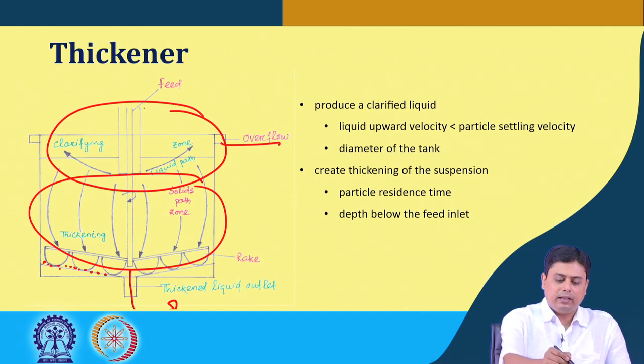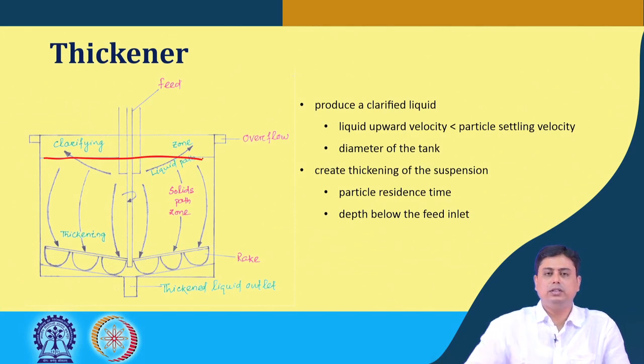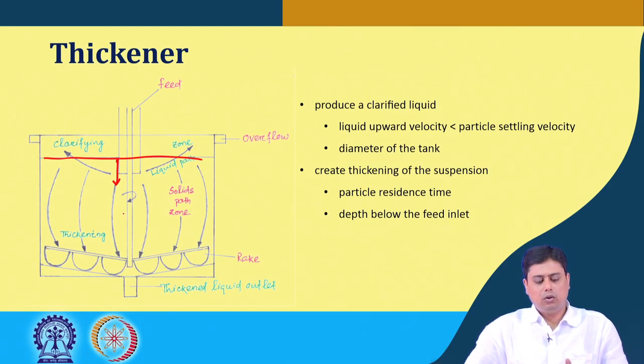Another vital thing is that the feed that comes in is not just left at the top surface of the pool of liquid. It comes down to a certain depth from the top surface of the vessel, and is introduced in a possibly less turbulent manner.